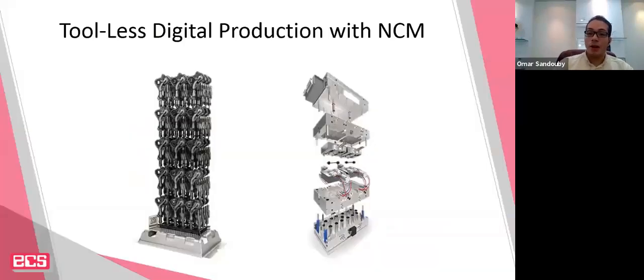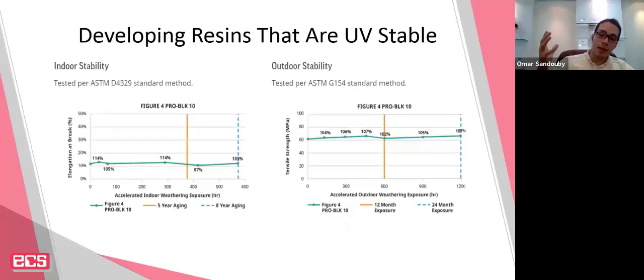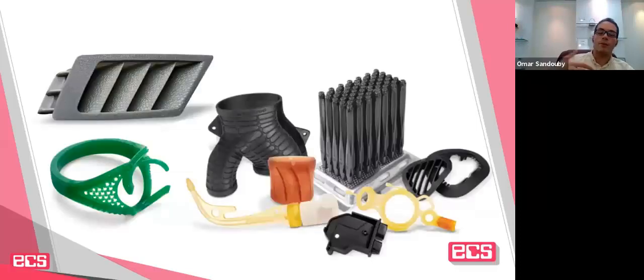We spoke about the non-contact membrane technology and how it allows you to now print hundreds of parts in a matter of hours and be able to give you resins or materials that can hold their mechanical properties. That always used to be the challenge way back then, when we couldn't get those parts to go into functional end-use applications. So we can produce all sorts of different textures and lattices and plastics that can take, let's say, 300 degrees C or go into medical applications. So overall, that was the trend.